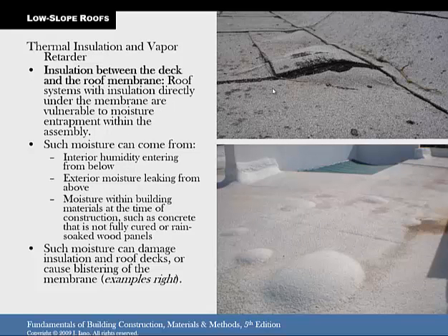Here's some roof problems, obviously. They had some issues causing bubbles. It wasn't sealed right, or there was moisture damage, and if they didn't do the proper sloping, like I said earlier, or didn't follow the manufacturer's recommendations, the manufacturer will not guarantee that, and they will just have to fix it on their own dime. But that moisture can come from below with humidity. There can be a pinhole in that roof surface, and it can seep in there and cause problems. Just a bunch of different ways it could happen.